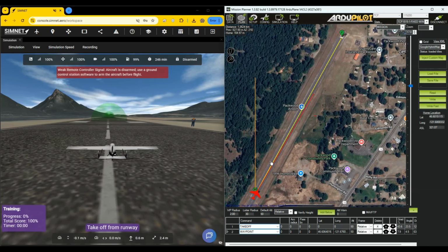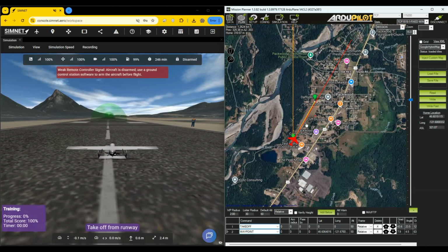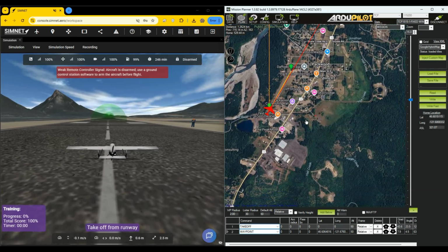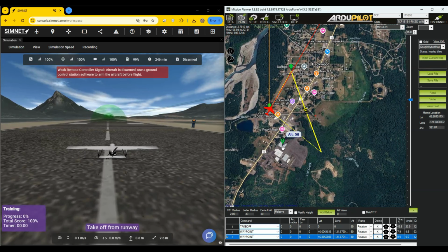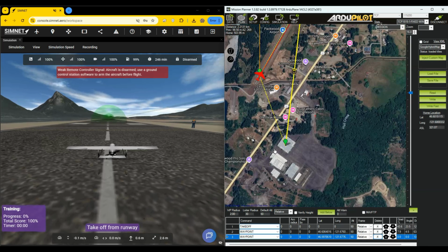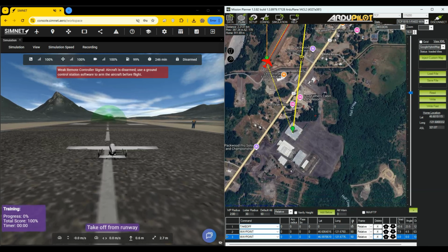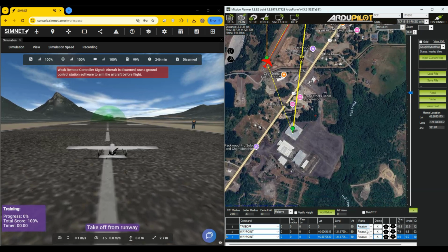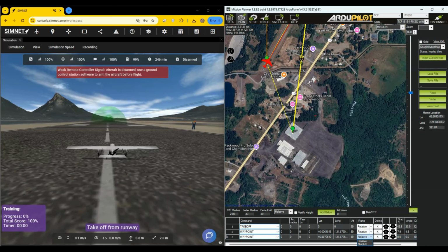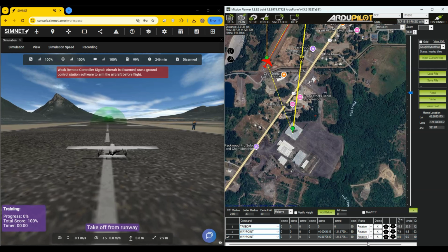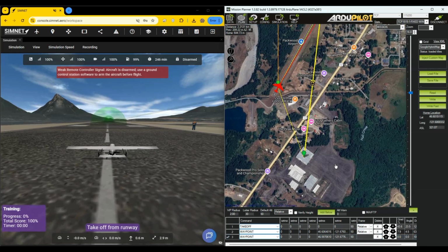After takeoff, we can place waypoints as desired to direct the aircraft to fly to specific locations and altitudes. You can use the table in the bottom to adjust the altitude of each waypoint and set the altitude reference frame. Use relative to indicate altitudes relative to the takeoff location, absolute to indicate altitudes relative to local mean sea level, or terrain for altitudes above the local terrain elevation.